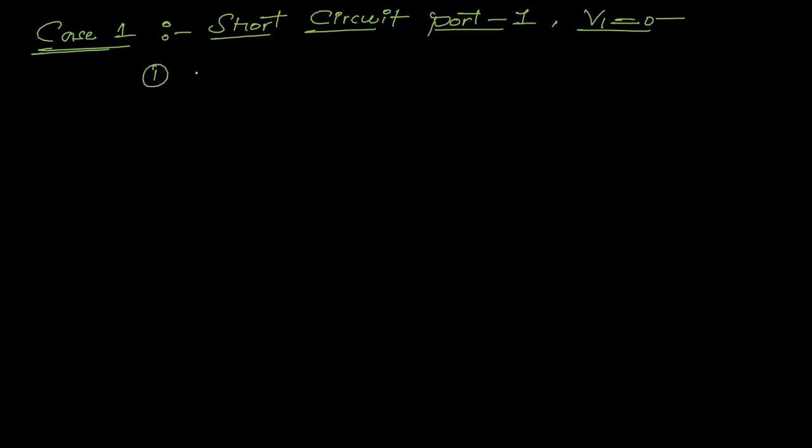From equation number 1, I1 is equal to Y11 V1 plus Y12 V2. In this expression, substitute the value of V1 is equal to 0.